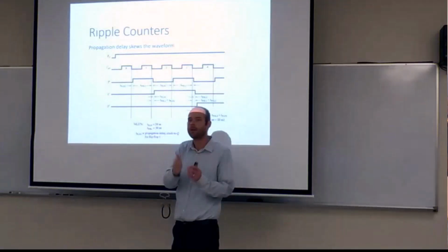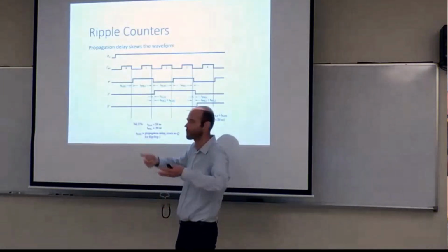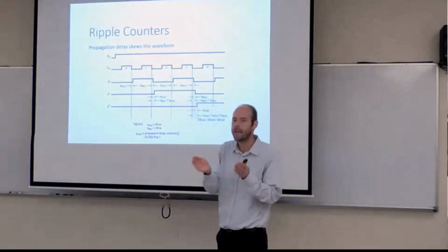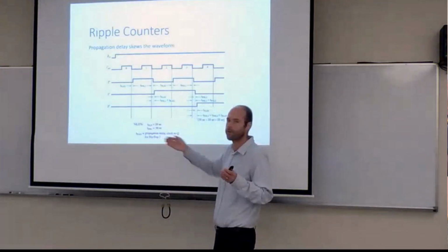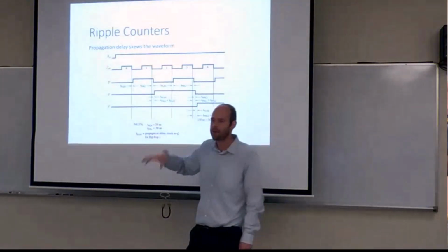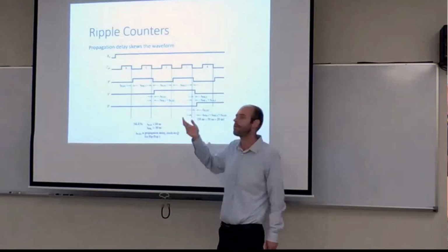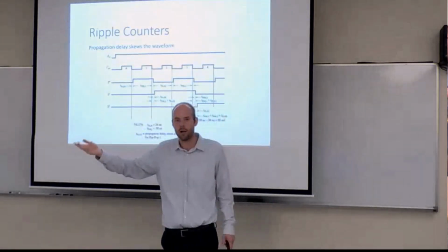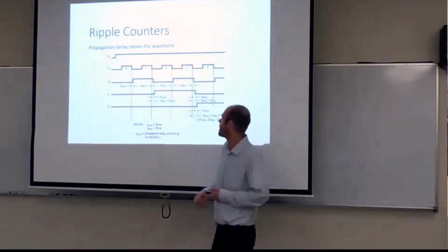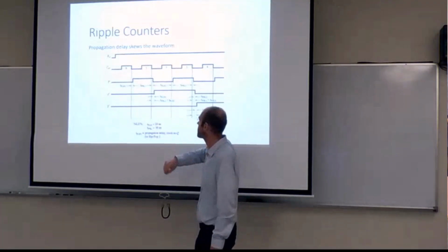And the time from when we get the input edge to the output Q change is referred to as the propagation delay. So how long does it take for the signal to propagate through the gate? In many cases, it's 20 or 30 nanoseconds. So quite fast to us as humans, but this is something measurable on our oscilloscopes. We can measure the delay of gates physically in the nanosecond realm pretty easily with our benchtop equipment.